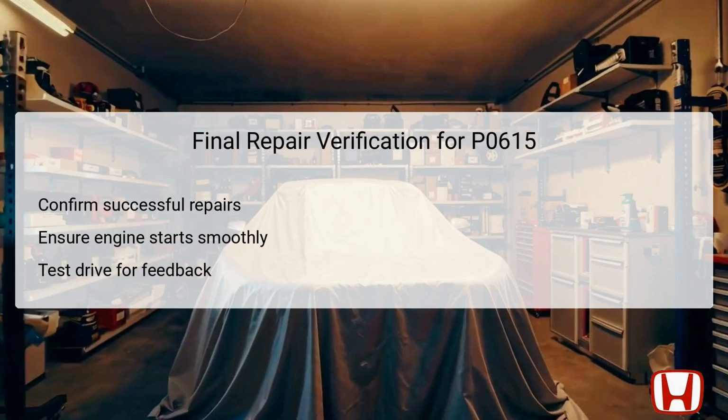After completing the troubleshooting steps for DTC P0615, it is crucial to verify that all repairs have been successful. Start by confirming that the engine can now start without any issues. This tests the integrity of the starter cut relay diagnosis circuit, as well as the associated components you've inspected or replaced. Also, conduct a test drive to ensure that the vehicle operates smoothly during various conditions.